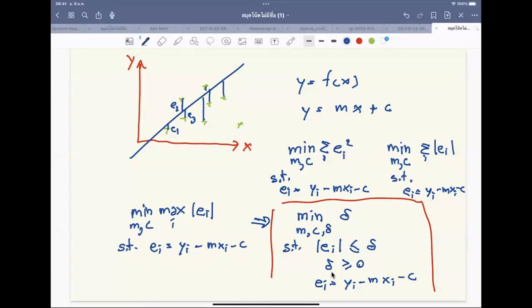However, our problem contains variability or disturbance. We have disturbance all the time. We don't know it, but we know that the disturbance can be between a certain range. So we can formulate the optimal control problem as minimax: we minimize the error, the deviation between set point and output, by adjusting the control action.